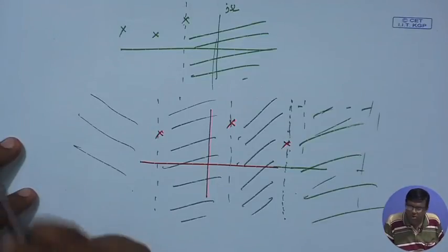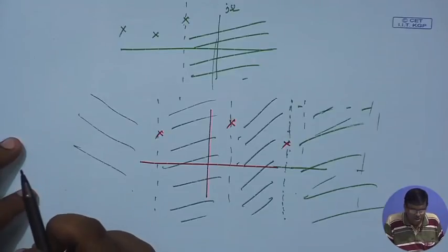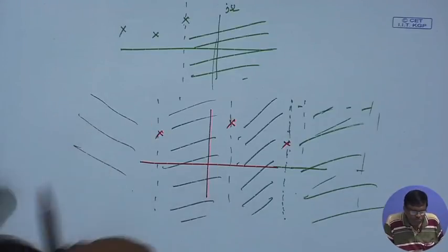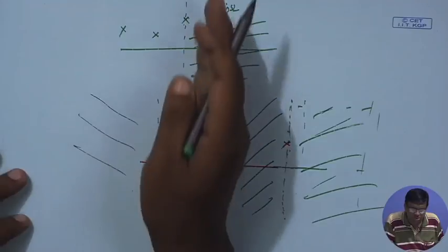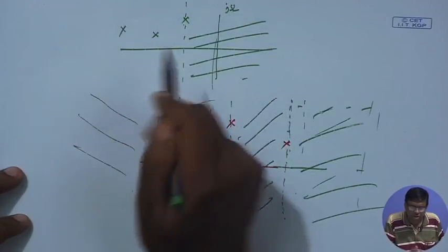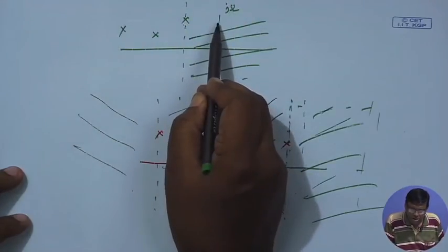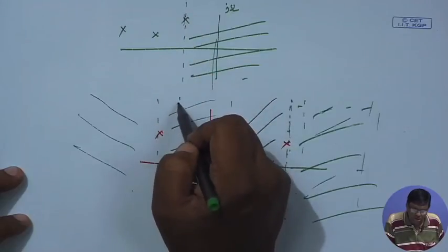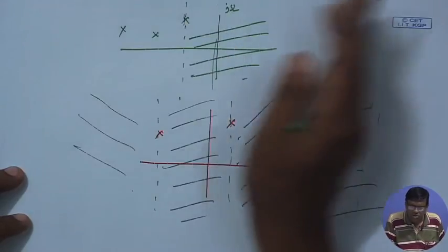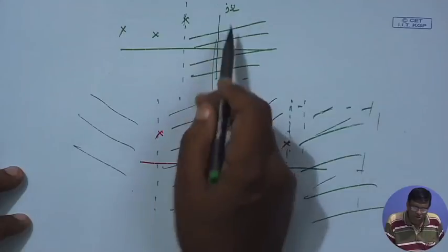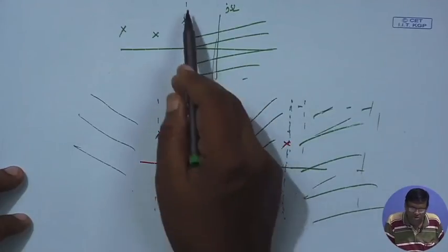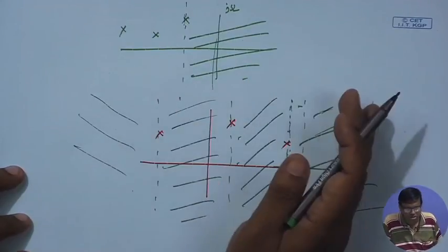So, for a linear and time invariant, causal and stable rational system, all its poles must be on the left half plane. You take the one closest to the j omega axis and draw a vertical line through it, and then go to the right side. From that, it will include the j omega axis and go to the right hand side of a vertical line. So, it will be both causal and stable.